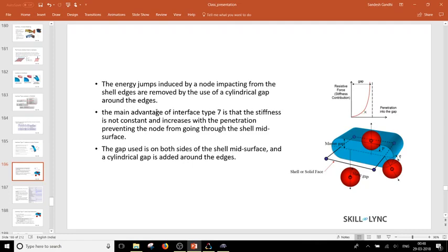If you see that the energy error is negative, that could mean that some of the energy is being used for the contact, so that the slave nodes can be kept out of the vicinity. So this is how you know where the energy might be going out, and how to rectify some of the energy errors.